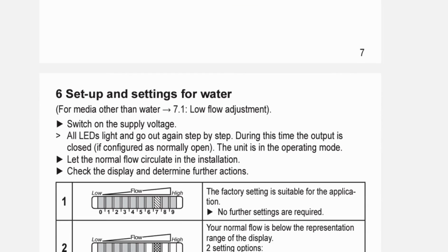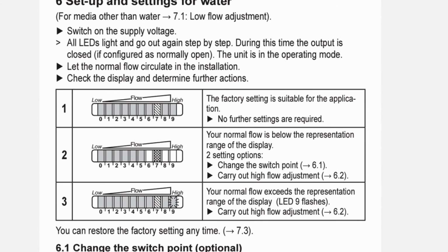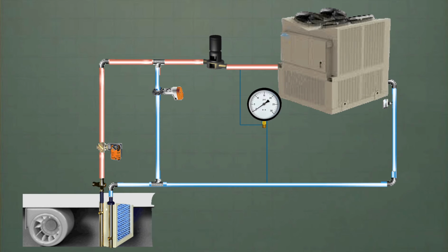For me, the flow switch was out of calibration, but it's also tripping on low suction pressure. So that tells me that we probably do have a flow problem. And so I'm going to dig a little bit deeper into this because I'm kind of paranoid and I don't like walking away from stuff and having callbacks. So after this point, now we know my transducers are accurate. I know my flow switch is accurate. I know that we have more than minimum flow going through the machine right now in its current operation. So this machine is also equipped with a bypass valve.